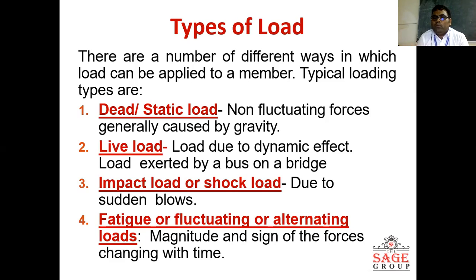Live load is due to dynamic effects, when you are moving. For example, the load exerted by a bus moving on the road or on a bridge is called live load. Impact load or shock load is due to a sudden blow. If a 5 kg stone is dropped from the first floor to the ground, the impact produced is called sudden load or impact load.